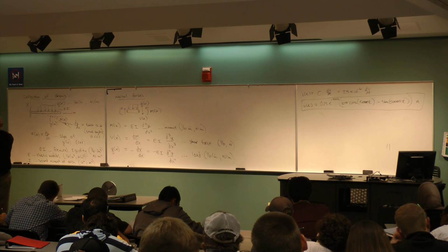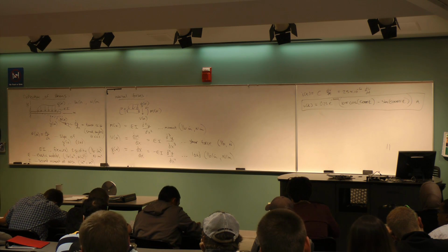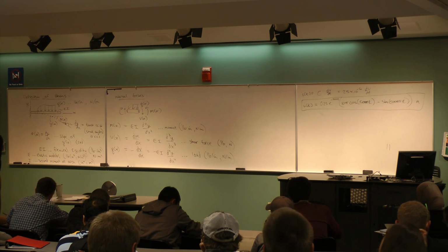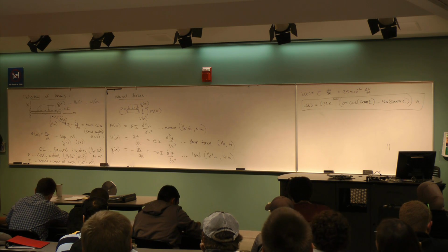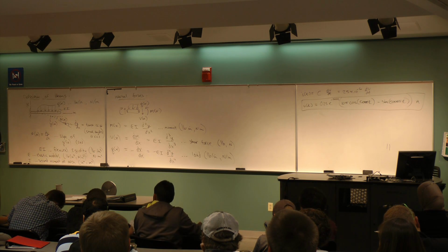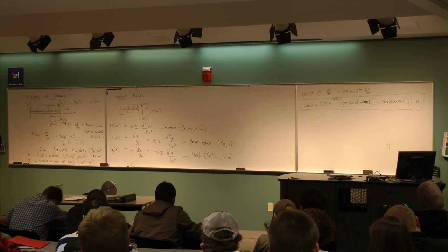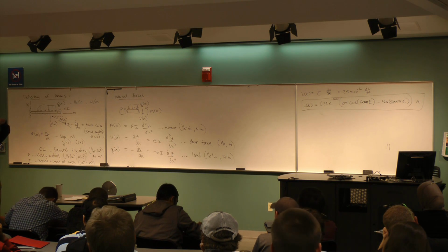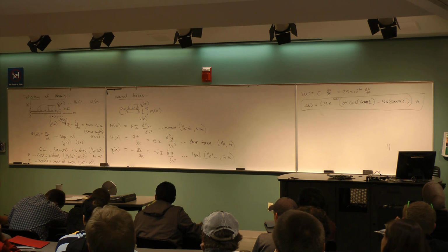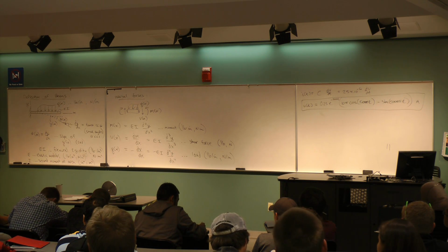So for example, if I go to bend this beam, this is a flimsy beam. And so I put a load on it and it bends an awful lot, not very resistant. Now look, this is the exact same beam. If I flip it 90 degrees like this and I try and bend it this way, heck of a lot harder. This is the reason why you look at beams for buildings, for example. They have a flange and a big web, right? I-beams. They're tall. Hard to bend things about the tall axis, right? As hard as I'm trying, this thing's not bending at all. If I flip it this way, now it bends. So easy to bend about the thin direction, really hard to bend about the thick direction.